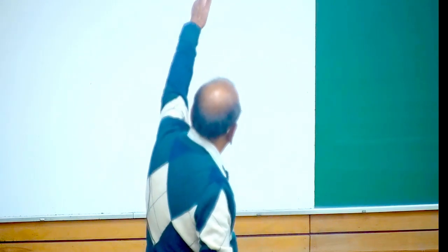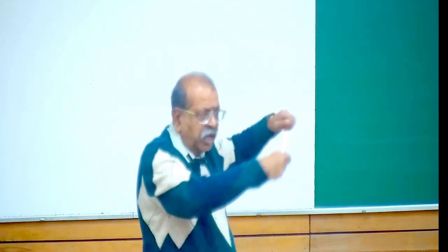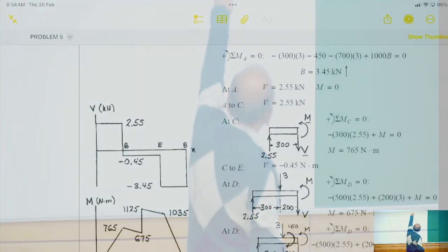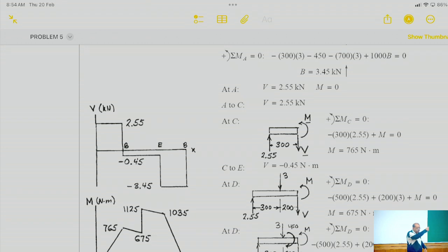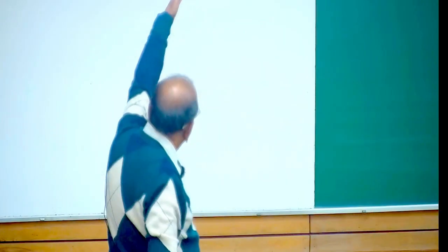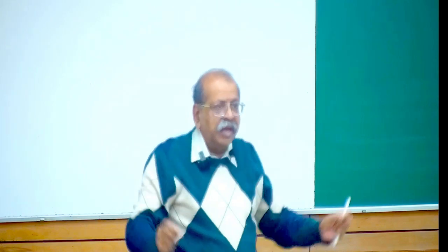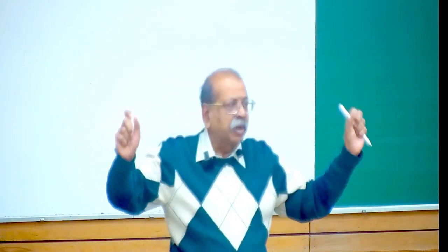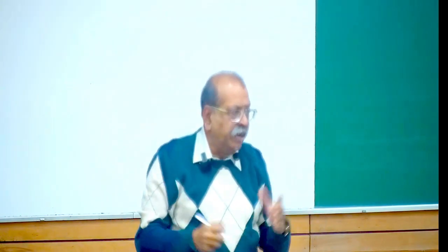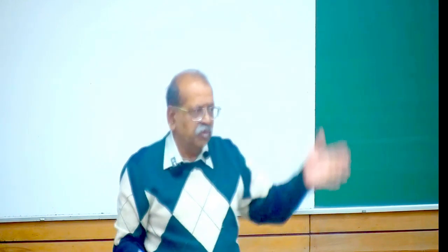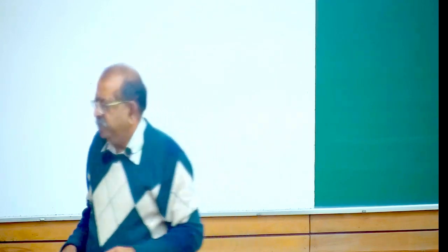There's a jump there. And then from B to E, once again the slope from B to D is the same as the slope from D to E. And then we go to 0. See, if at the two ends there are supported ends, then the bending moment has to be 0. So we got it.